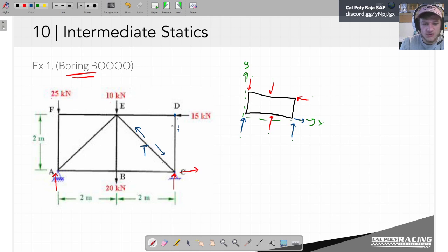However, why do 2 free body diagrams when we can do 1 free body diagram? So, what we're going to do for the method of sections is we're literally going to make a section. I'm going to do my section in red. Red seems like an appropriate color for sections. I'm just going to section off the diagram here. I'm going to treat my whole problem as if I now removed this part of it. And whenever I remove something, I have to replace it with something else equivalent.